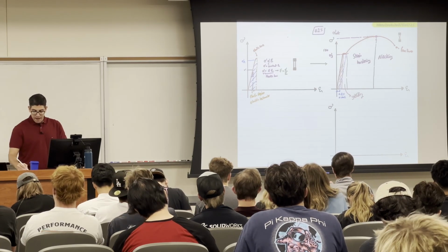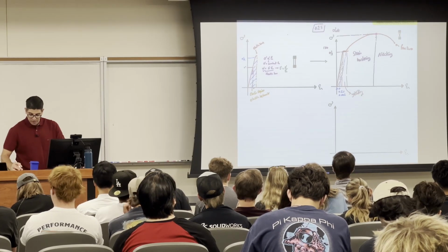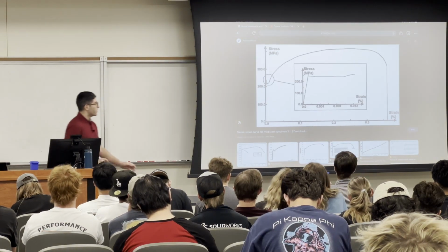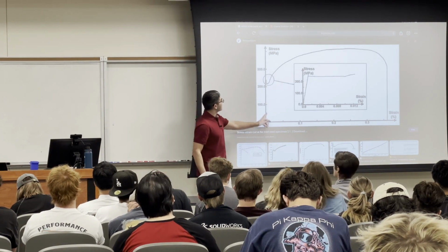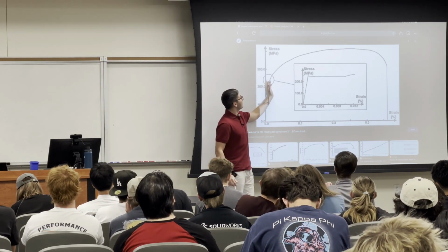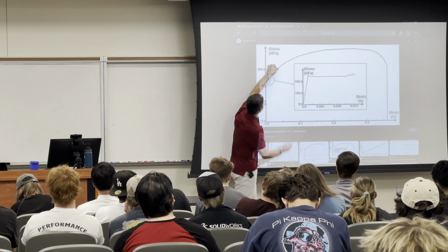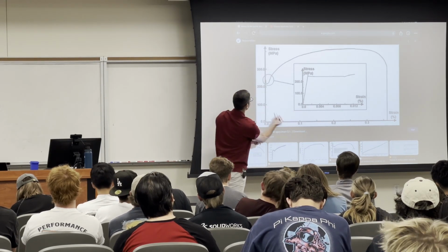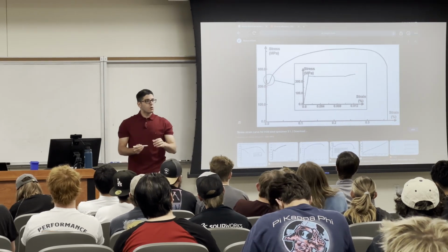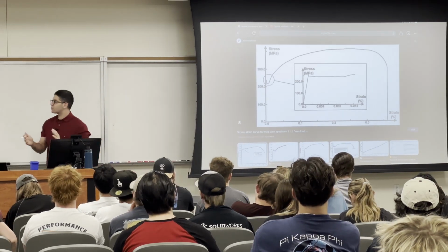But if you look at what's happening here, I'm actually exaggerating when I draw this stress-strain curve. I want to show you something from the curve. As you can see, the linear elastic region is barely vertical. But once you go beyond the yield, if I apply a stress in the steel, a small difference in stress gives a very big difference in strain compared to the linear elastic region. Do you see what's happening? So at strain hardening and beyond the yield, the material is going to resist more forces, but look at what's happening with the strain.